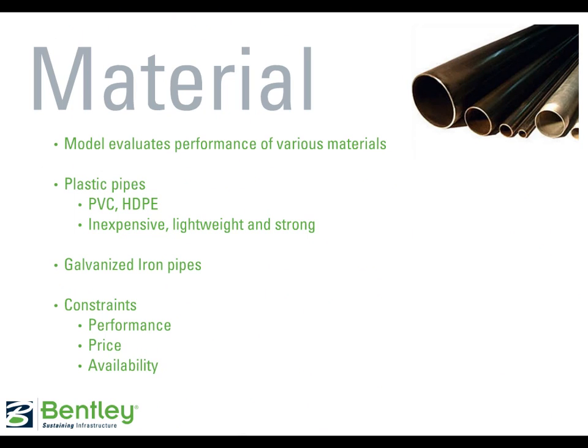You can use your WaterGems model to evaluate performance of different materials in your system. Plastic pipes, including PVC and HDPE, are common because they're typically cheapest and have good performance. Plastic pipes are comparably lightweight, immune to corrosion, resistant to abrasives, and available in many countries around the world.